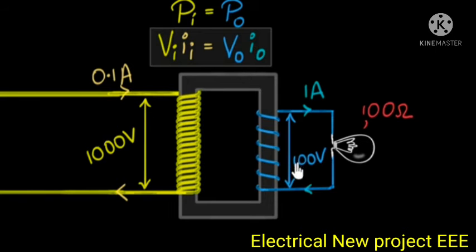Ohm's law? Well, we need to be careful. Ohm's law works within a circuit. So over here, if the voltage increases, current will increase. Voltage decreases, current will decrease. But here we are comparing voltages and the currents of two different circuits. They can have whatever values they want. So don't compare voltages and currents of two different circuits and think about Ohm's law.